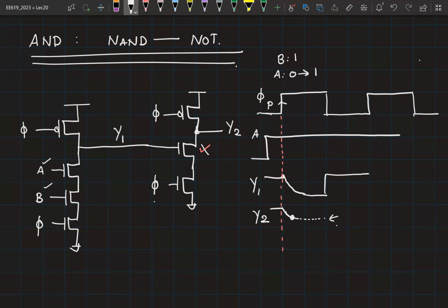So we said that individually the gate will work fine as long as you ensure that the input is always a rising edge during an evaluation phase. But the moment we put two gates together, we see that the second gate output is failing, even when we ensure that the first gate has the right sort of input. What do we do now?